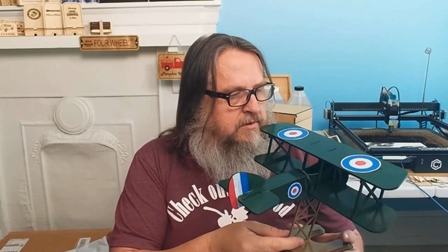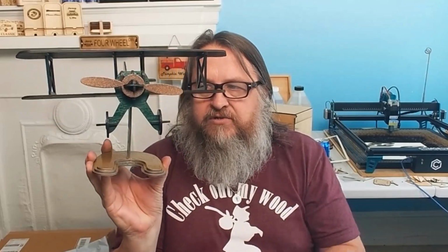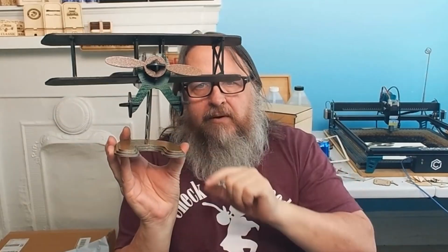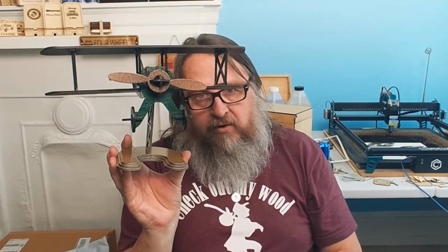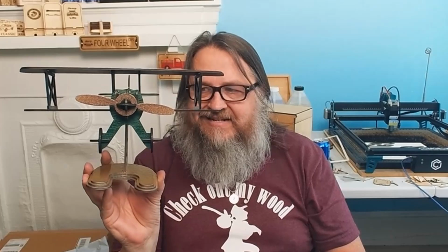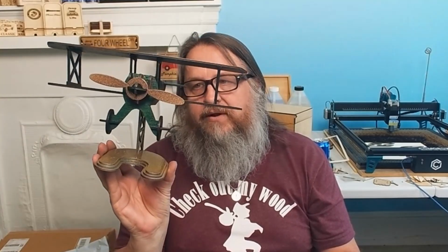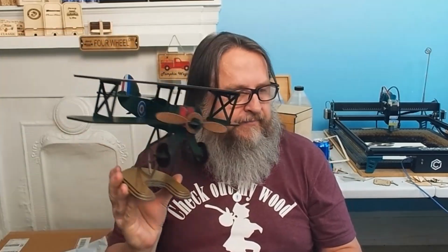You can use your change slots and tabs in selection to change your slot size. And using 1.5 millimeter basswood, you see that this single support does support this okay, even with all the extra weight of the paint that's on here. But if you wanted to make it a dual support, it's easy enough just to duplicate that, add another slot, and position that in the center of the fuselage, and you'll have two supports. Not a very difficult thing to do. But I like the look of one. It's cleaner, simpler, and gives more of an illusion of it being up in the air.